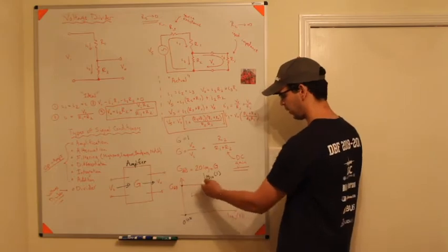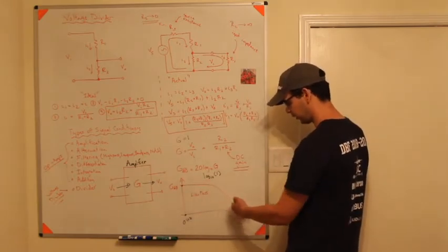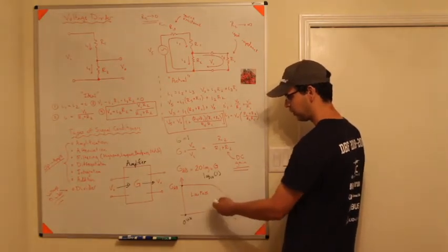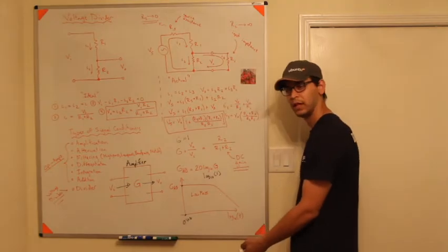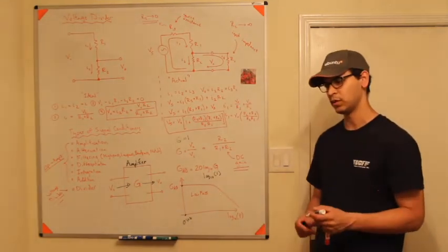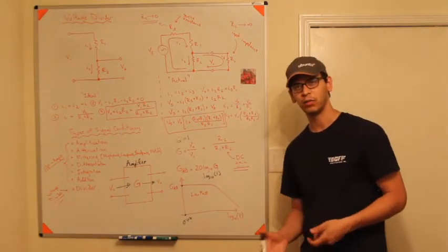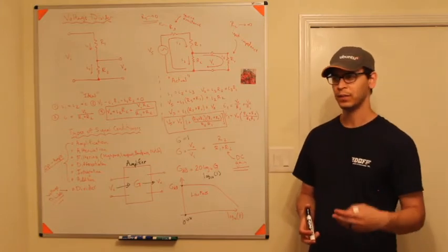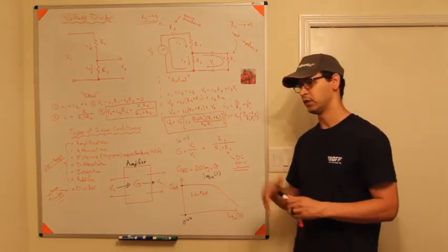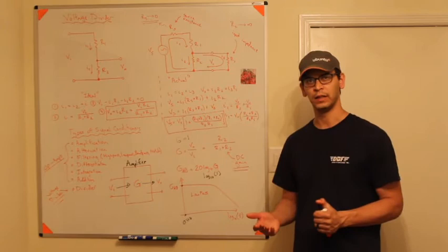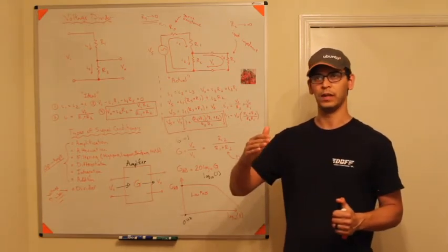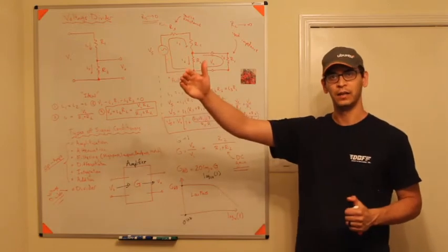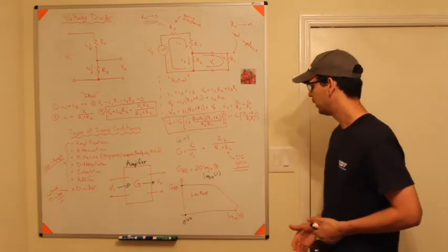And then if I have a low pass filter, if it filters the signal out, this means that the decibels are actually going to be negative. And so you might see in certain situations something like -3 or -6 dB, versus if you're listening to a rock concert or something, it's like 80 decibels. That's something where the gain is higher than 1, right?